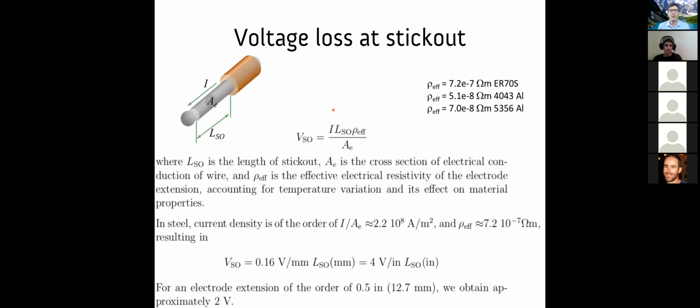All right, so let's get into what we haven't discussed in the previous class, the stick out. The stick out is so important. For example, if you read the Lincoln Procedure handbook, it will tell you the problems they had with high currents and stick electrodes, shielded metal arc welding electrodes, because the current is going through the whole stick, and sometimes the welding rod can get so hot that the flux coating starts to peel off. So what we're discussing is very universal.